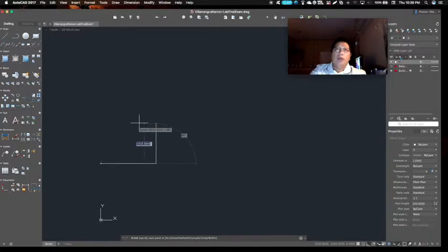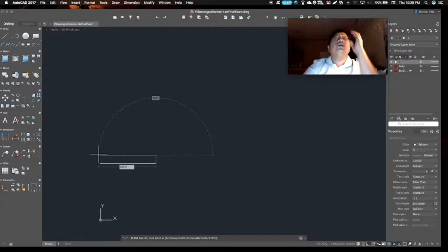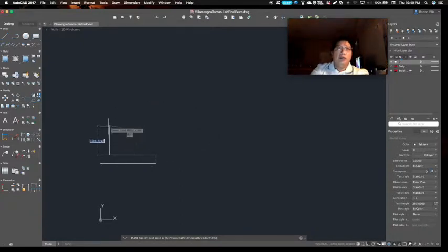Then we go up by 300, the width of the wall. Then we go to 1650 to the left. Sorry if I do it that way, I cannot see it. And then go up again by 300. Then the thickness of the wall is another 300. Is it 300 already? Okay, 300. And then we close it. C. Okay, so that is our first wall.